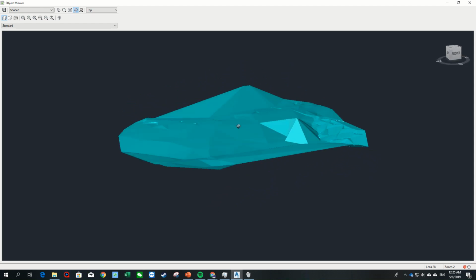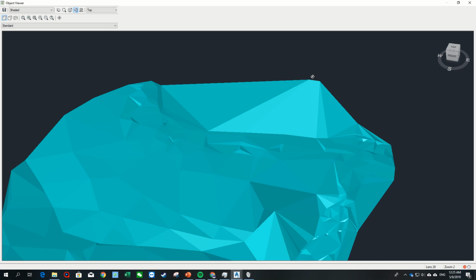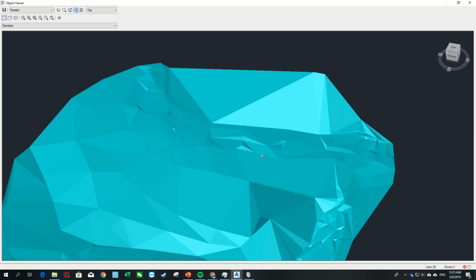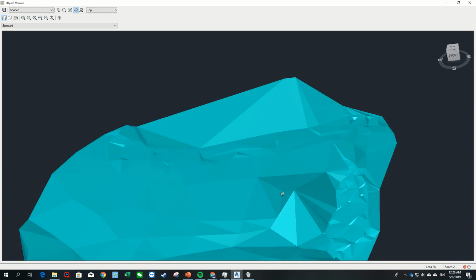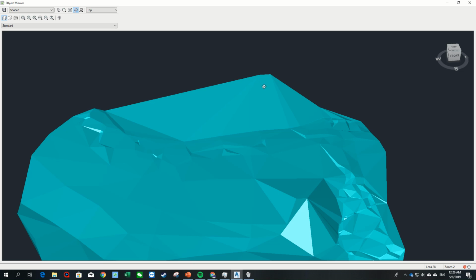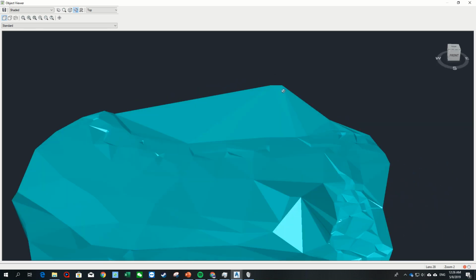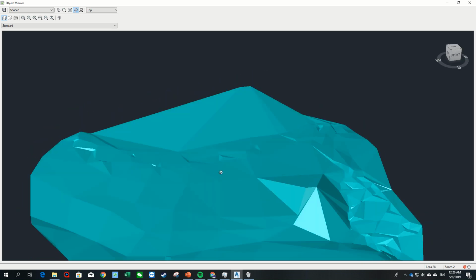As we can see, there are 2 points here and 2 points at this point that are not correct. So you can either choose to correct the value or just delete the point only. For myself, I prefer to delete the point, because this point will cause the meshing to differ. So this will give a very inaccurate result.